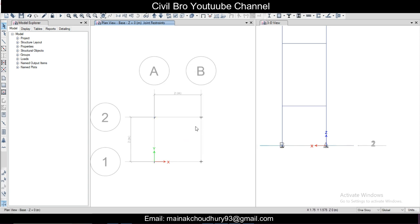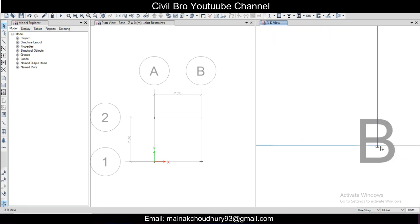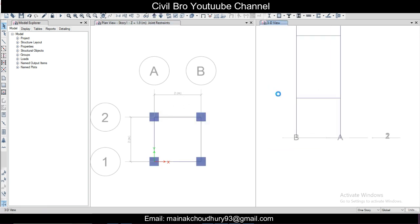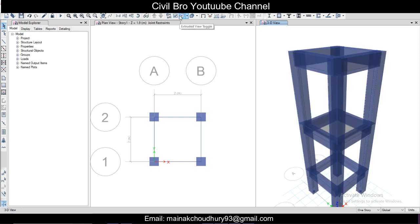So then we just hover over it a little bit, you can see the sign has been changed from hinge to fixed. So once this has been done, you can see in the 3D view also, click on 3D for the default 3D view, and click on this extrude option. You can see it easily.